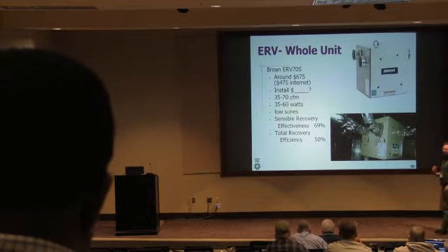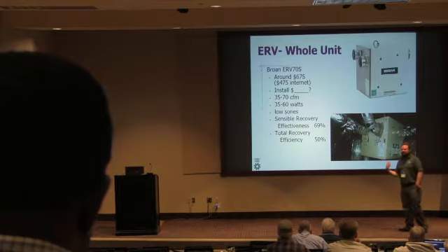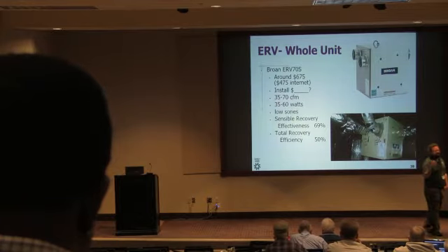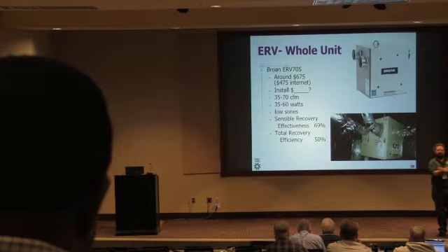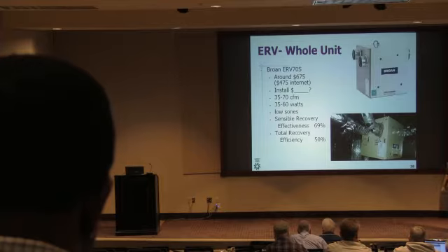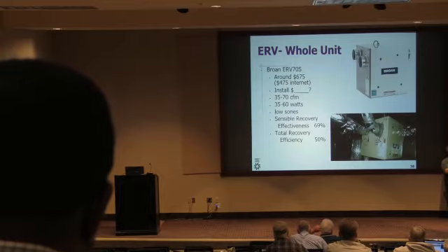It's not going to bring air all the way down to the temperature you want it to be. It's not going to fully dehumidify either. It's just going to do a little bit of tempering of the incoming airstream with the outgoing airstream. But it is an energy recovery ventilator because it's recovering energy from your exhaust stream and sinking it into your incoming stream to give you a little bit of tempering.